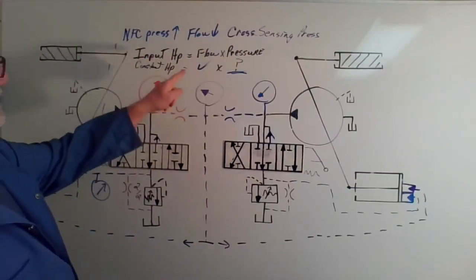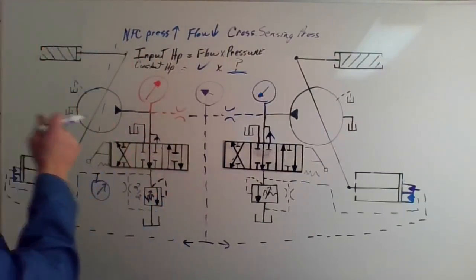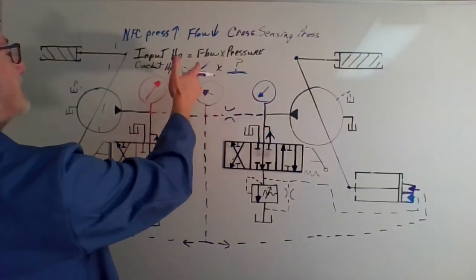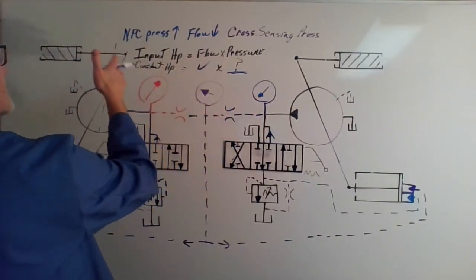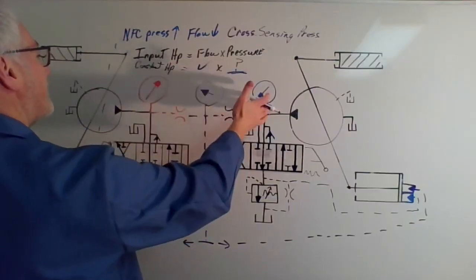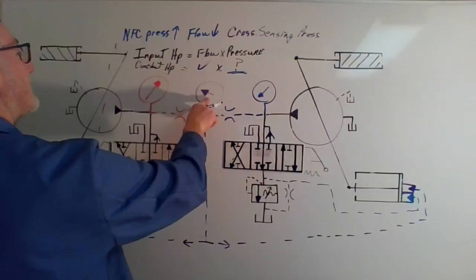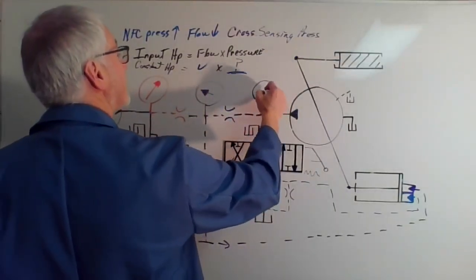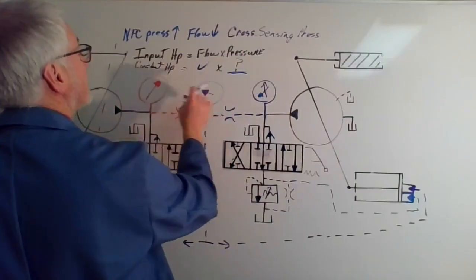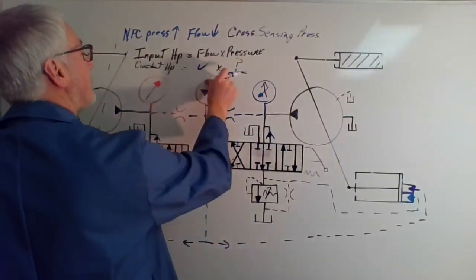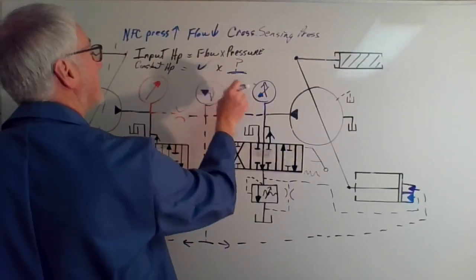And in fact, the cross-sensing pressure is beautiful in this way because it's finding a happy place in between the two. And it's really dictating that I know the load on this pump at any given time, and I know the load on that pump at any given time, because that will have an influence on what this is. If they're both loaded by chance, if this one's up here and this one's up here, well then this one is going to be somewhere up there as well. So they will always be talking to each other.